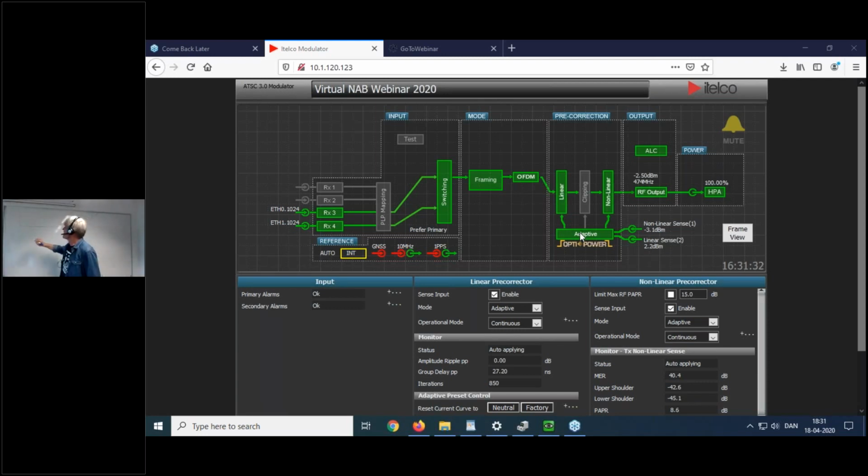I will try, yes. If we try to draw a baseband OFDM signal, it is bandwidth-limited noise, so I don't know how much better to draw it than something like that. Such a signal has maybe an RMS around here, and the peak can easily be, let's say, plus 12 dB.